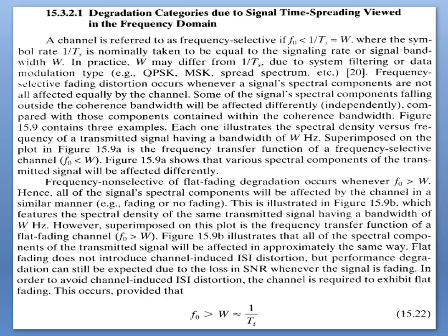It is fair to say a mobile radio classified as exhibiting flat fading degradation cannot exhibit flat fading all the time. As f0 becomes much greater than W, less time will be spent in that type of condition. By comparison, frequency selective fading is independent of the position of the signal band, and it occurs all the time. Fading occurs all the time and not just occasionally.